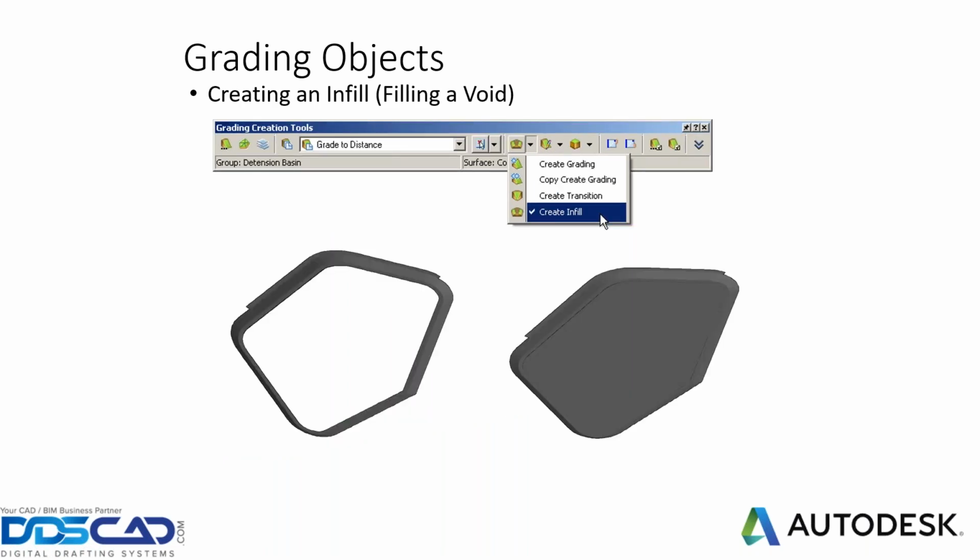All right, grading objects. When we talk about grading, we'll talk about something called an infill. As you can see here, this is before I put the infill. As you create your grading objects, if you don't create an infill, your surface will actually look like this. So if you're doing volume calculations or doing contours for, let's say, just a site plan, it will not show through here. So you want to make sure you create the infill. We'll go over these examples as well.